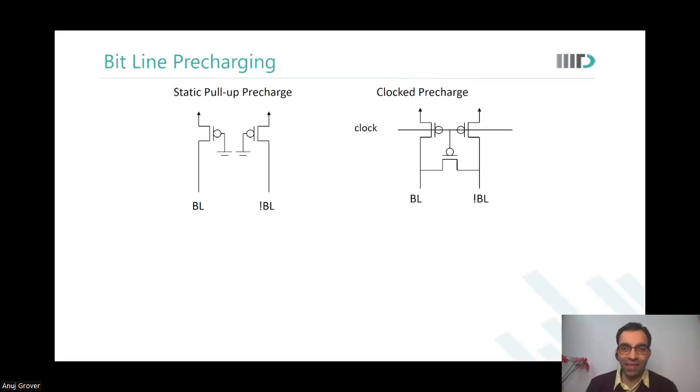Okay, and this is an internally generated signal. Yes, this is an internally generated clock. Typically, you will call it the precharge clock. So this clock will typically go to the precharge circuit. Whenever the active read or write cycle is happening, the precharge would turn off.